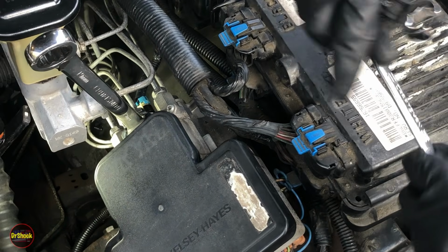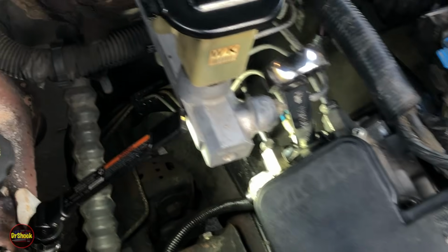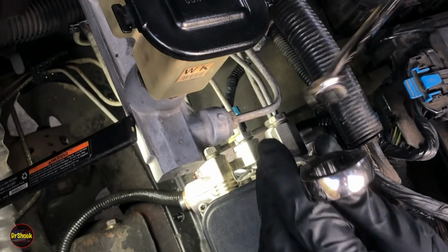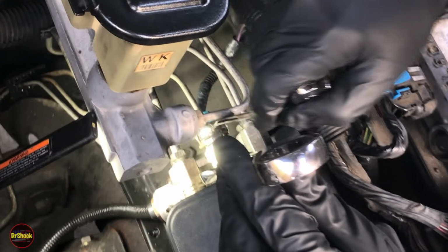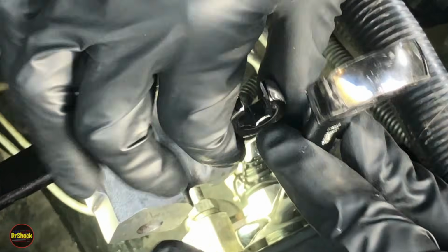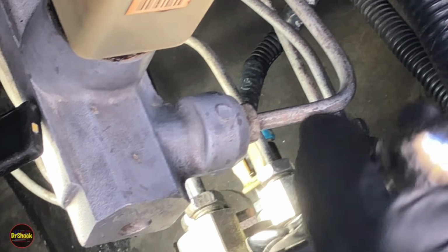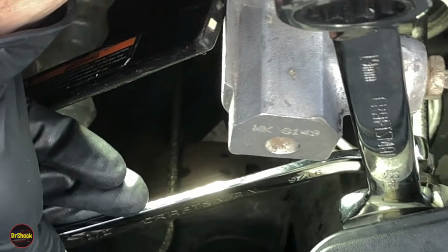Now, all this really entails is coming in with the line wrench initially. We can show this one in the middle here, which is probably the best camera view. We're just going to work this in here. There's plenty of room here in order to get this loosened up, and plenty of room in here to tighten it down when the time comes. Similarly, when we do this one on this side, we'll come in from this angle. If we look through the top here with the camera, we can see that the line wrench fits perfectly right onto the fitting like we would want.